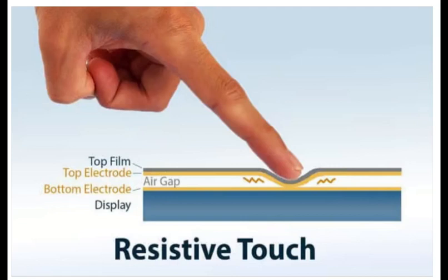This decrease in capacitance is detected by sensors located at the 4 corners of the screen, allowing the controller to determine the touch point. Surface capacitive touch screens can only be activated by the touch of human skin or a stylus holding an electrical charge. Advantages: better image clarity than resistive touch. Durable screen. Excellent resistance to surface contaminants and liquids, dust, oil, grease, water droplets. High scratch resistance. Disadvantages: requires bare finger or capacitive stylus for activation.